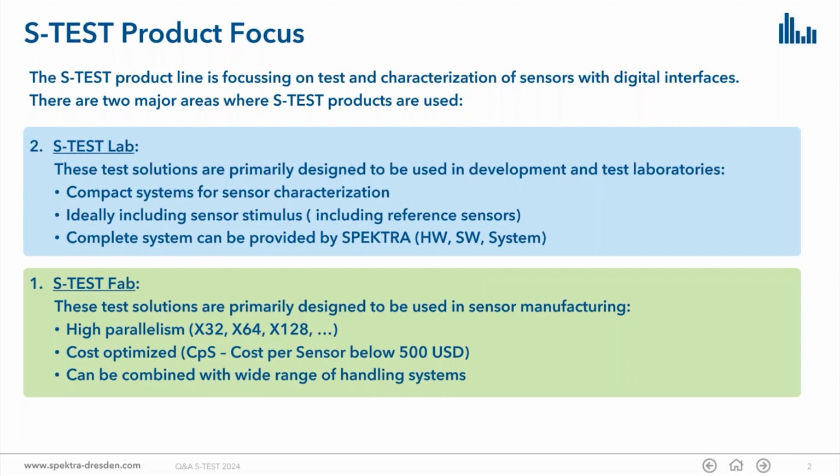Part of the S-TEST Lab setups can also be shock test systems for testing basically the robustness of designs, the robustness of PCBs, even anything that is system related, like how strong is your cable fixation to a PCB? Are my soldering pads big enough because my product is supposed to see high G acceleration forces? Things like that are covered by S-TEST Lab.